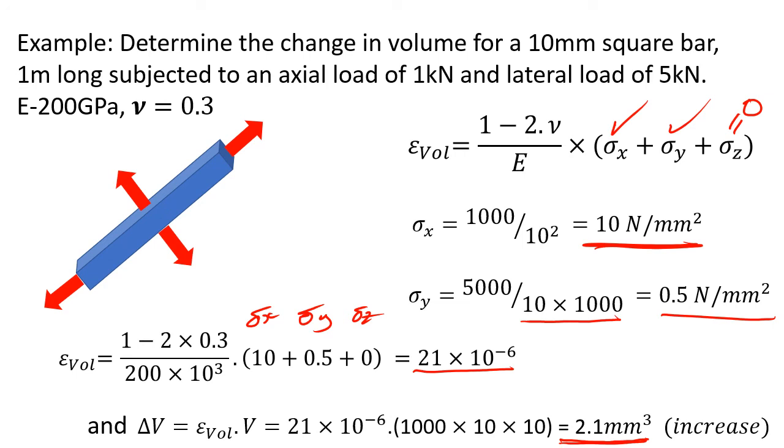So you might first think, well, putting a 5 kilonewton load on in one of the other directions would make a huge difference. But hopefully you'll see the reason it hasn't made such a big difference is, although it's 5 kilonewtons, it's applied over a much bigger area here. So if we try and highlight that, it's applied over a much bigger area, so it actually doesn't really create a large additional stress in the component.